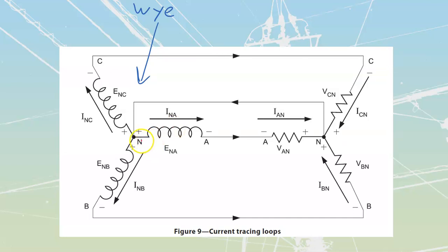Remember, this voltage is going to go and alternate. Right now it is negative, positive. But that's just because we've frozen time because it's AC, then it's going to go into positive, negative, and back, forth, etc. But right now, we're just going to look at it while it's got the positive over here and the negative across there because they're saying, look, we always want to do our first subscript where the current is entering. So if the current is entering at N, we're going across to A, so we're going to get this ENA.